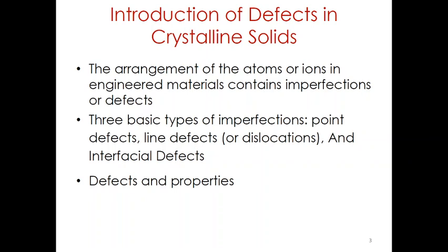For example, the new ceramic superconductors under certain conditions can conduct electricity without any electrical resistance. Material scientists and engineers have made long wires or tapes of such materials. They have also discovered that although the current flows quite well within the grains of polycrystalline superconductor, there is considerable resistance to the flow of current from one grain onto another across the grain boundary. On the other hand, the presence of grain boundaries actually helps strengthen metallic materials.